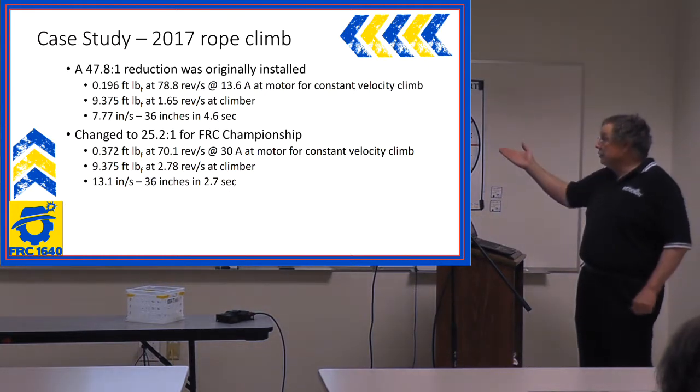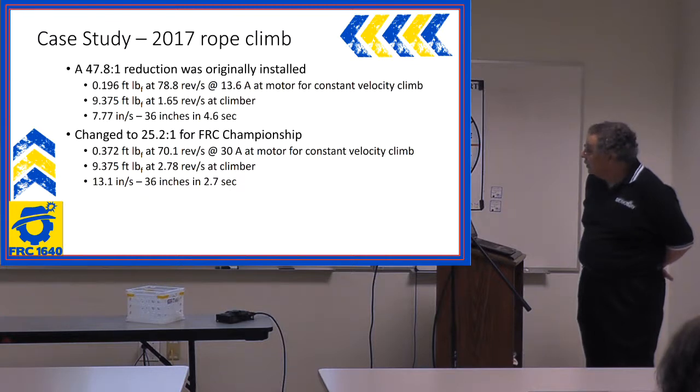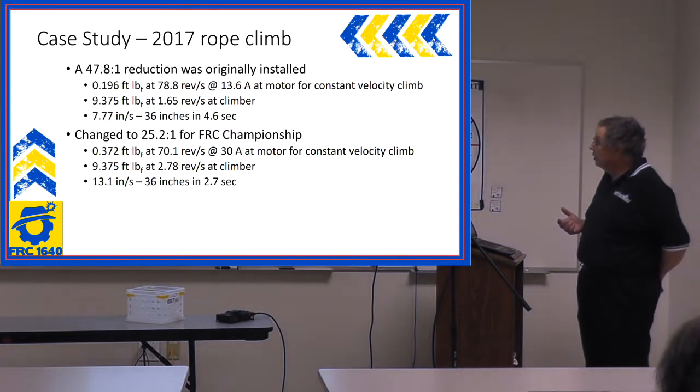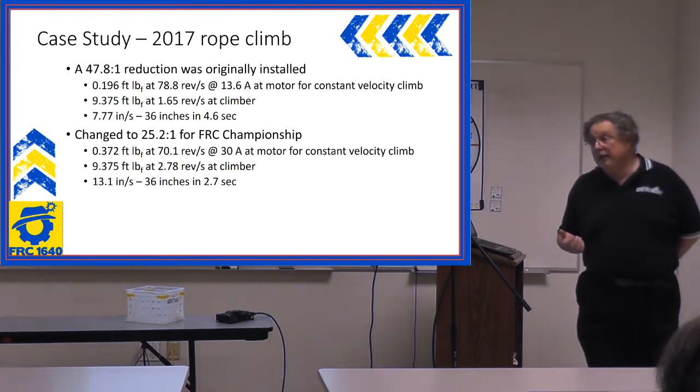Based on the curves, at 48-to-1, the motor was putting out 1.96 foot-pounds of torque at 79 revs per second. It was drawing about 14 amps.